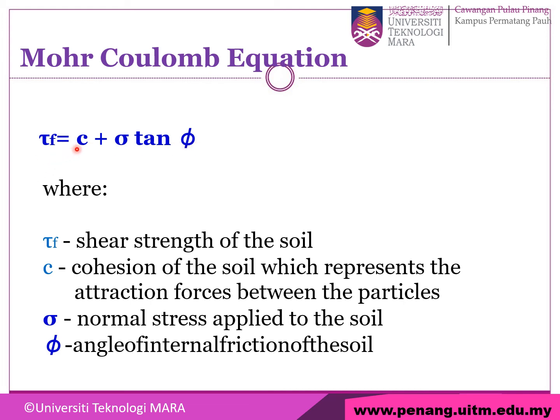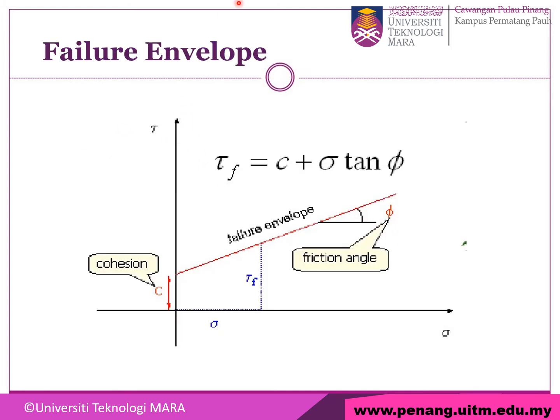Shear strength is equal to C plus stress tangent phi. This is what the failure envelope looks like. This axis is shear stress, tau, and this axis is normal stress.